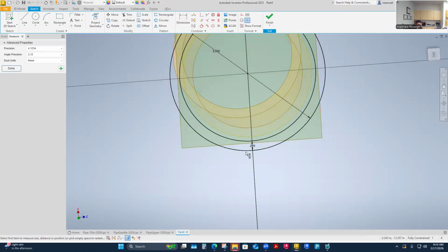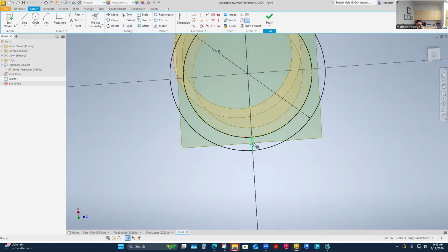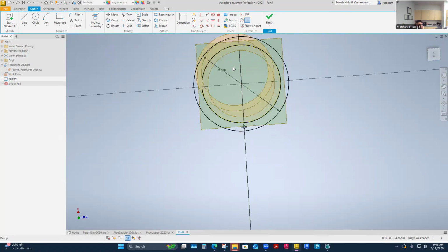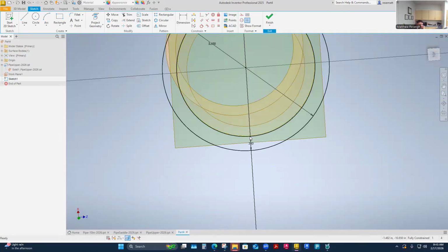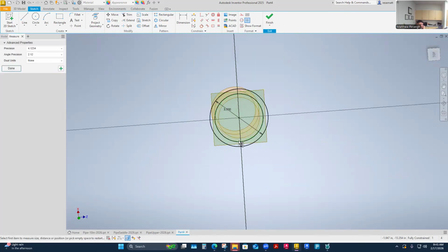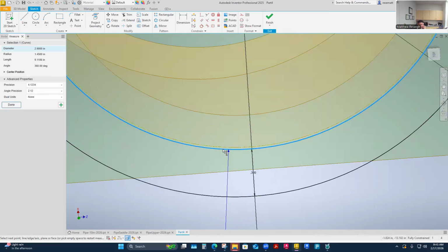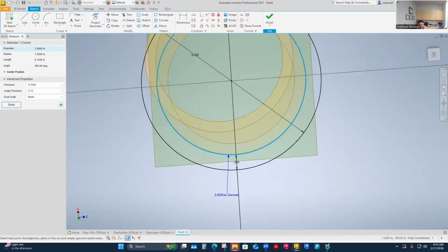While I'm in my sketch, I would change this to 0.3 if I get schedule 80. Now what kind of gap do I have? There's still a gap. How close is this? I need to see my diameters. That chart probably gives me my diameter, but I can just look at it. It's 0.29, and this one is 2.875. So it's really a difference of 2.9 now.